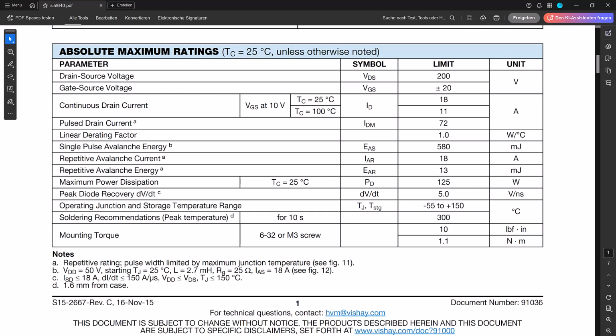Junction temperature range -55 to +150 degrees Celsius. Beyond 150 degrees Celsius, the structure starts to degrade irreversibly. You see a pattern. Every limit depends on temperature. That's the central theme of any power MOSFET. Ignore temperature and your simulations will look pretty while the real part blows up on the bench.